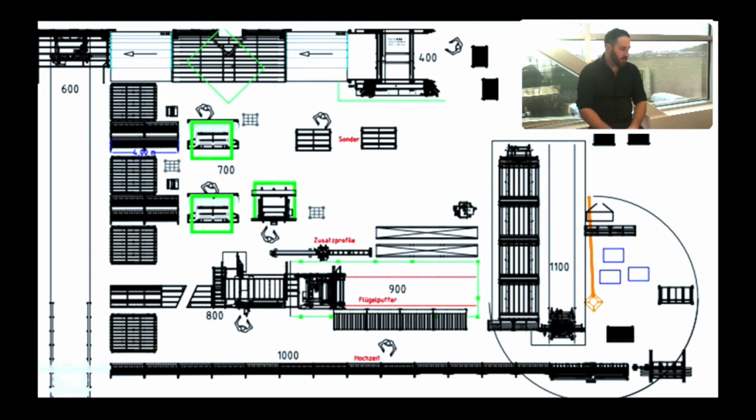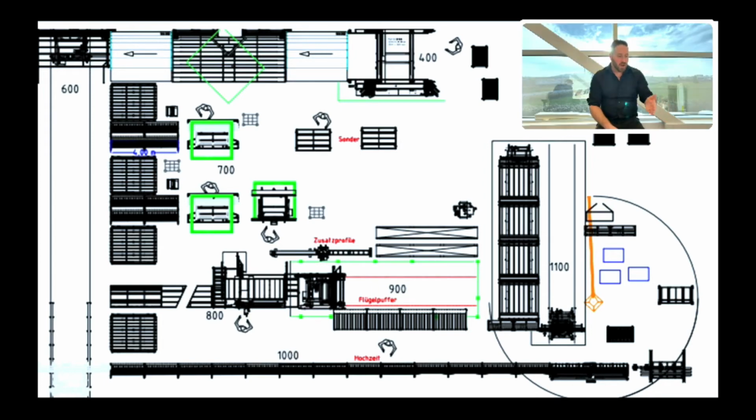The buffer is going to bring the frame all the way down on the screen to the vertical table there. Then a sash is going to come out of the welder and go directly to the last assembly table at the bottom of the screen. The employee there is going to be doing his assembly on the sash. The sash is going to be automatically unloaded to a magazine of different sashes.